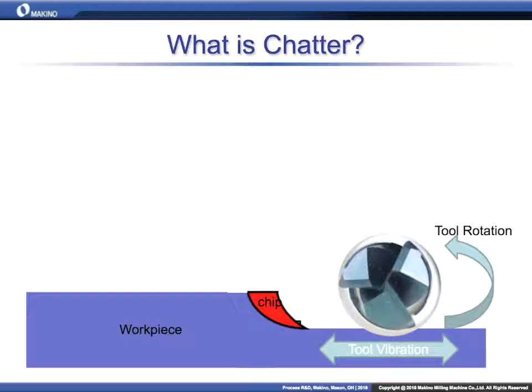And then you feed your tooth, advance it, the feed per tooth, and then your next tooth is going to try to shear off the left side of that chip, right? And if everything was stiff, really perfectly rigid, it would be something like that. Exactly, and that's kind of the mental image that is not easy, that I find a lot of people have. That tool, because you can't see it moving, it's not moving. But it is moving, it is vibrating, nothing is rigid.